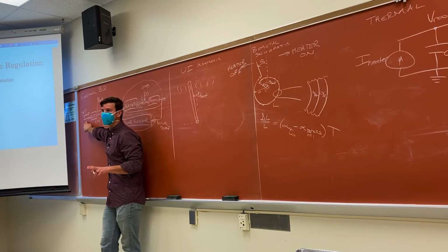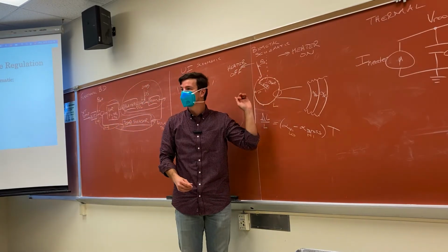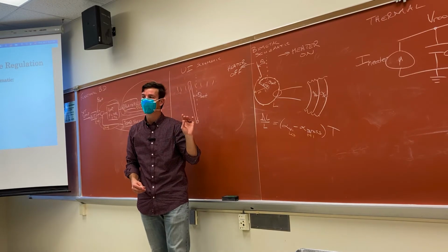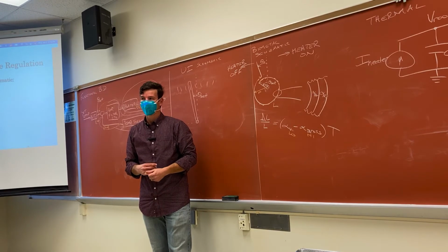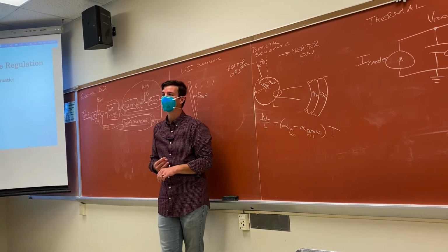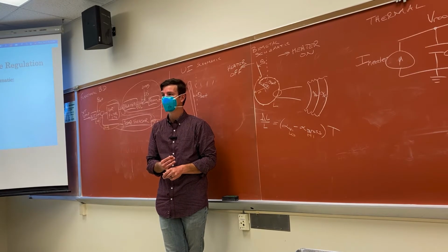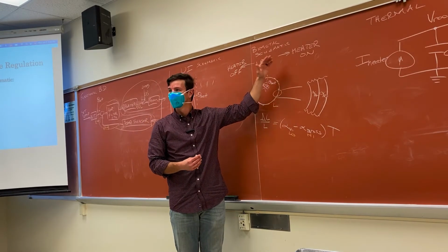The temperature in the room then does its thing to expand or contract the coil, which then adds to or subtracts from theta O. So once we set the temperature, let's say we don't touch it anymore, theta set stays at that position, and then if it gets colder, then we want the heater on, so the coil expands, and theta O only moves that way. Yeah, good.